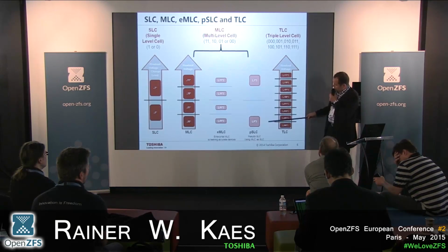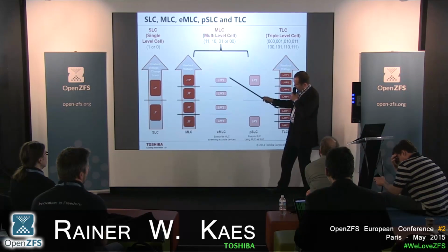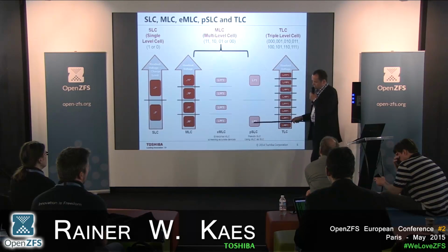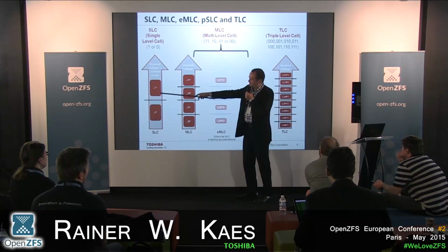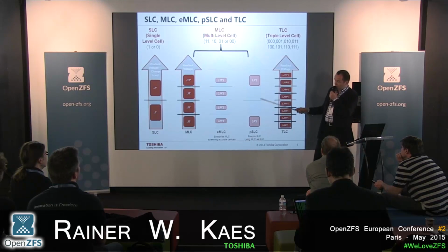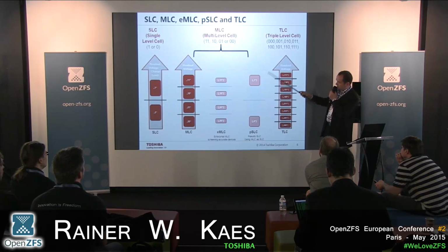One other technology is called pseudo SLC, and this is just using the normal MLC technology and writing just one bit. It's somehow going back to the earlier technology, but on the same physics as MLC. And here, obviously, if we write a full charge, we can tolerate many erase damages until we are at the wrong level. So this gives a very robust structure.